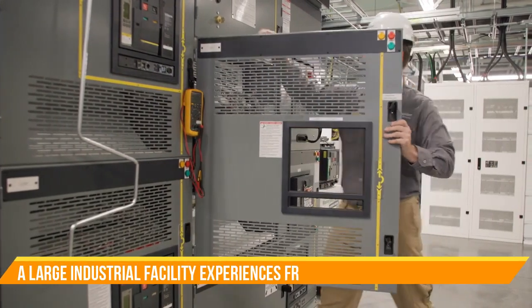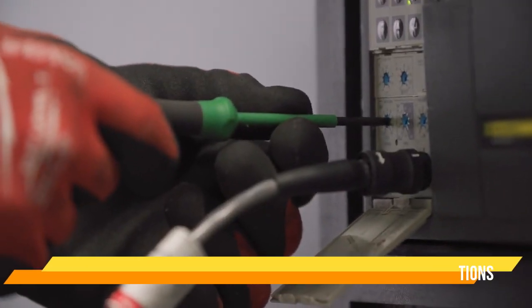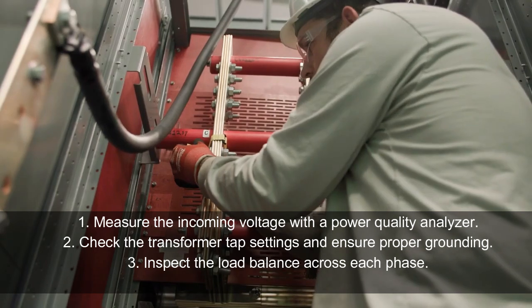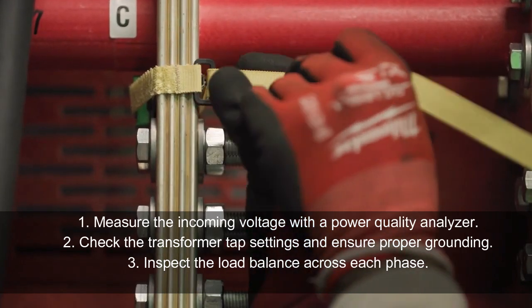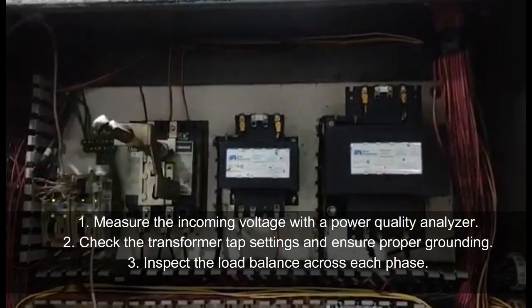A large industrial facility experiences frequent voltage fluctuation. How would you diagnose and resolve the issue? Number 1. Measure the incoming voltage with a power quality analyzer. Number 2. Check the transformer tap settings and ensure proper grounding. Number 3. Inspect the load balance across the phases.